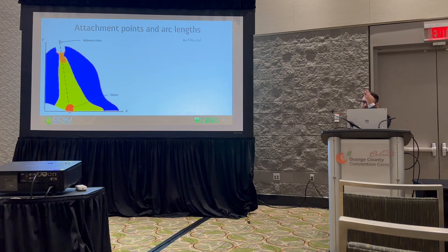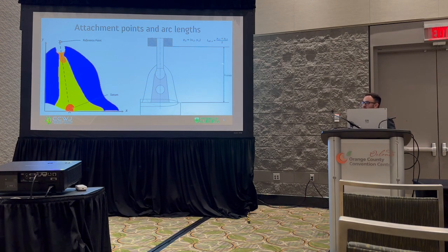If we draw a line between these two points, we can divide the arc into two regions, the left and the right. If we obtain the maximum, or highest, point of each color, we can take an average of the Y coordinates to get an average arc length from the datum. The contact tip to workpiece distance we define as part of the experiments, so that's fixed and a known value for us. So now we can start extracting some data.